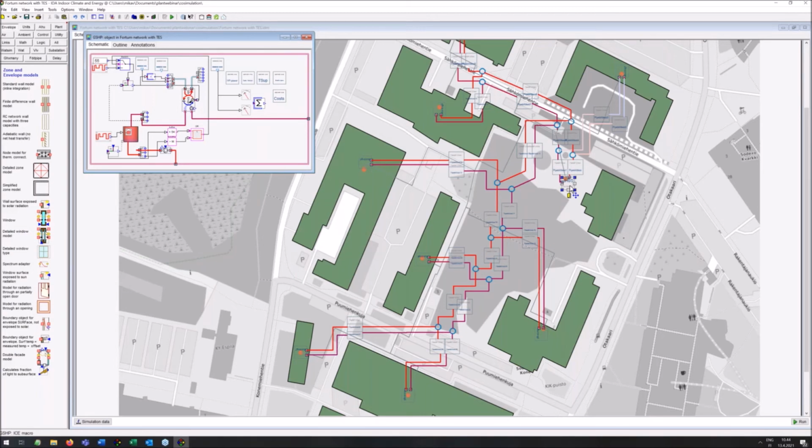And this is an air to water heat pump. The liquid side is connected to a big tank. And with this tank, we ended up in this project with 15% energy cost savings once we are charging that tank in the early morning hours when the electricity price was the lowest. So on an annual basis, we will end up with 50% savings in heating electricity with that heat pump.